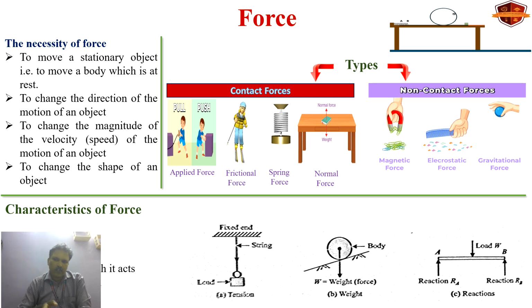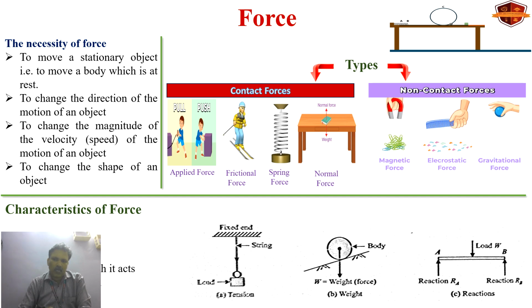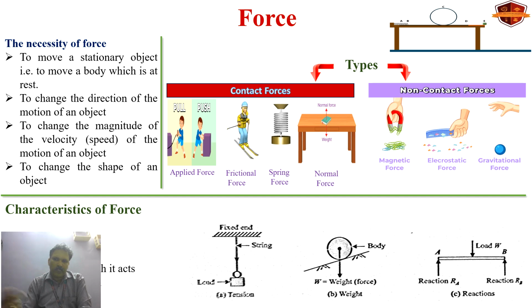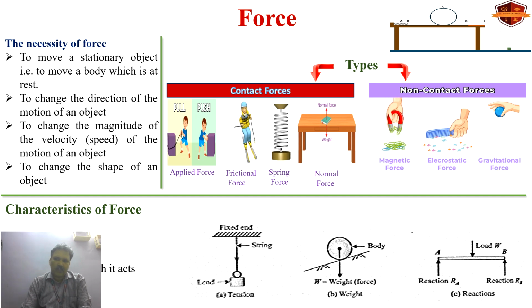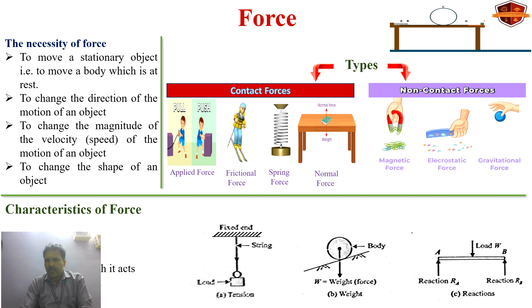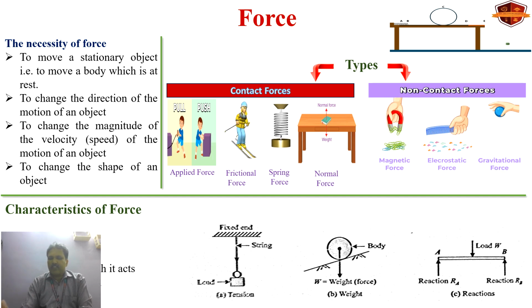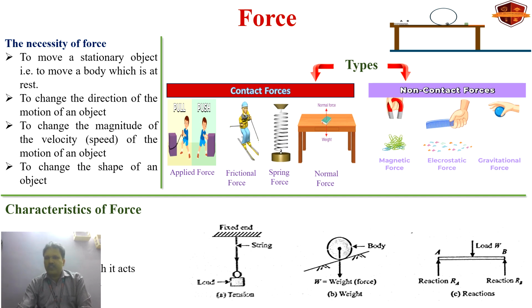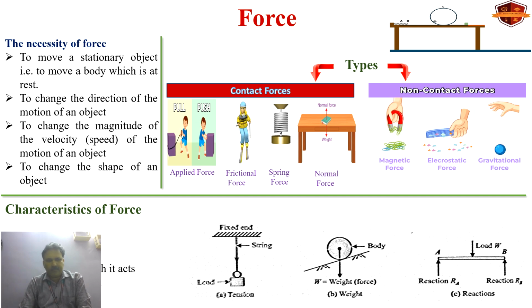Because we are applying some force with that stick on one ball, automatically the force will be transmitted to the next ball. That is the line of action concept. That is the principle of transmissibility. The force will be transmitted along the same direction of the line of action to the next object. That is line of action.